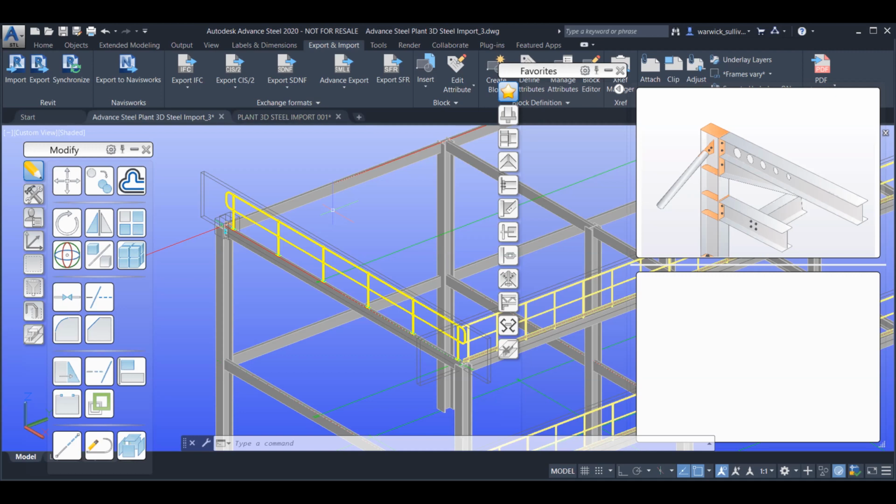But if you're outputting 2D drawings, and for the steel itself, you can't go past Advanced Steel. But Daniel, if you're doing high-level plant layouts and stuff like that, you probably don't want the nut and bolt detail in there. You just want length, size, and width and stuff like that.